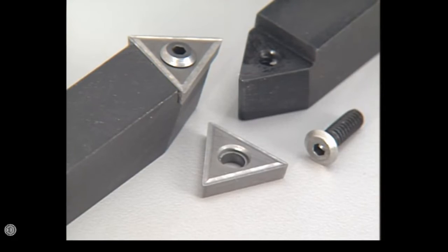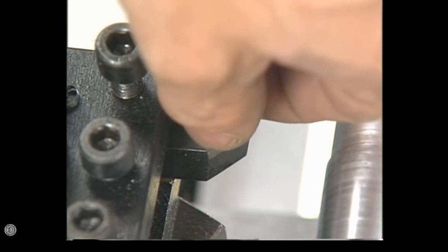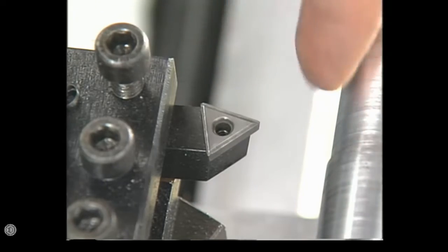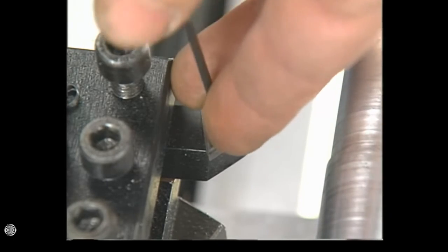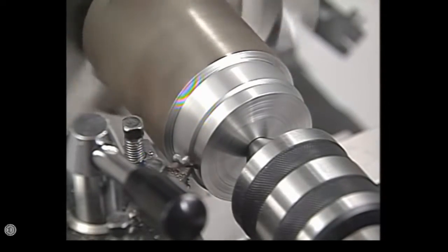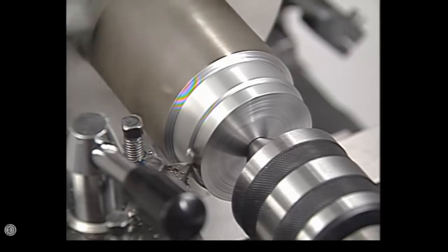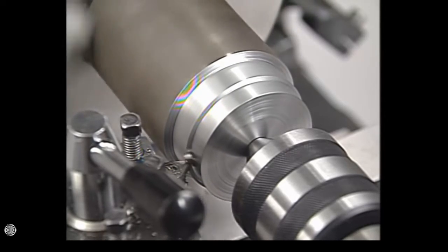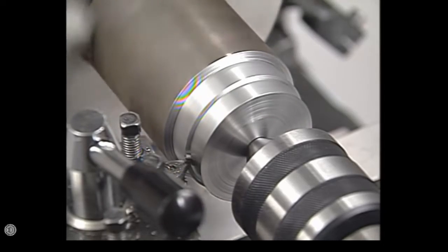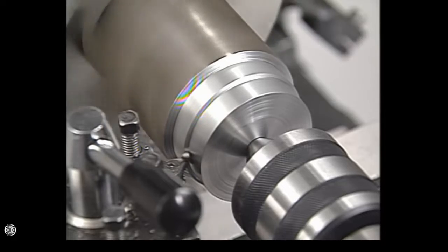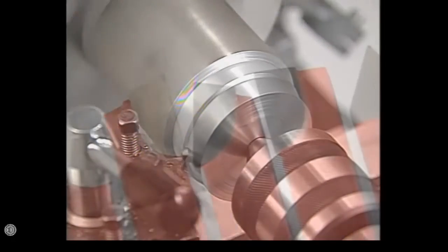This style insert is manufactured with a cutting edge on each of its 3 sides. After an edge is dulled, the insert can be unclamped and rotated to the next side. After all the edges have dulled, the insert is thrown away and replaced by a new one. Although this type of cutting tool was designed for the demands of high production work, it's really a great tool for the beginner because it allows even the person with little or no tool sharpening experience the ability to easily maintain a properly formed, sharp tool.